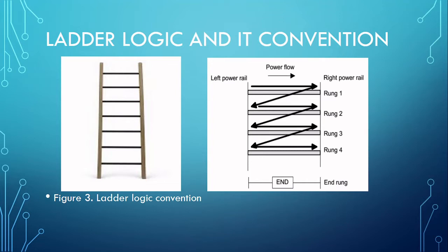And one particular thing about ladder diagram is that every component, be it your input or your output components, is identified by its address. Now in ladder diagram, the address always has an alphabet and a number. So it's a kind of alphanumeric method of writing a program. Now the alphabet depends on the manufacturer of that PLC.